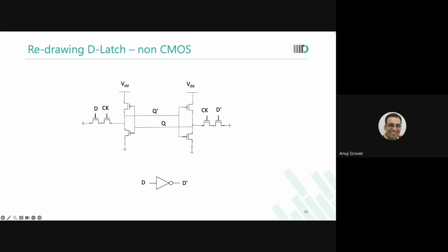Why? Because I will select memory cells with a clock, but I will not select just one memory cell at a time. I will select memory cells which are organized in one particular row or one particular column at a time. So if I want to do any more sharing, then I could probably do that with the clock inside. And what we also notice is that all the cells, so this one, for example, has an inverter which converts D to D bar, and this D and D bar are not shared in a horizontal manner, or we are putting it in a different way.